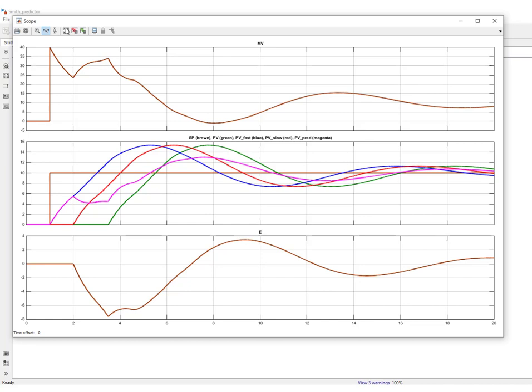So if you implement a Smith predictor, well, you'll have to pay a lot of attention at the estimation of the delay. But again, here, if you look at the curves, it's kind of obvious from the output of the overall model here in red and the actual PV that you have made a mistake in the delay. So by observing the curves, you can correct the parameter estimation.